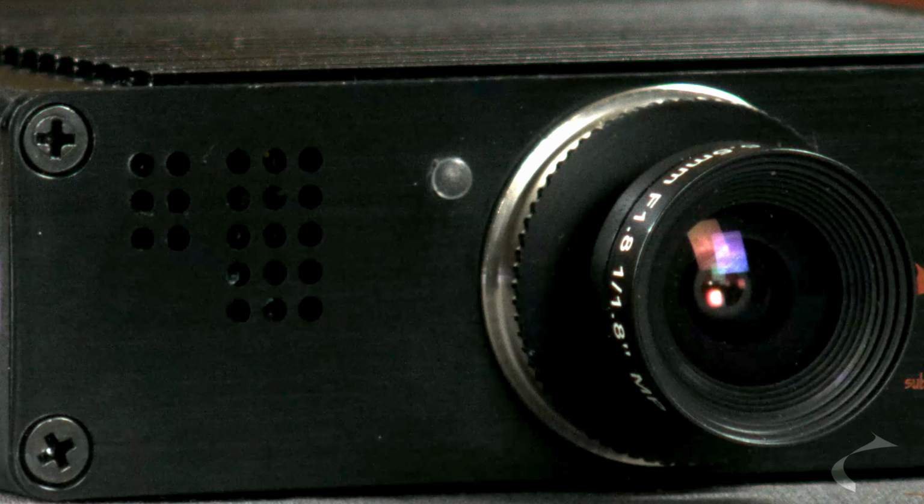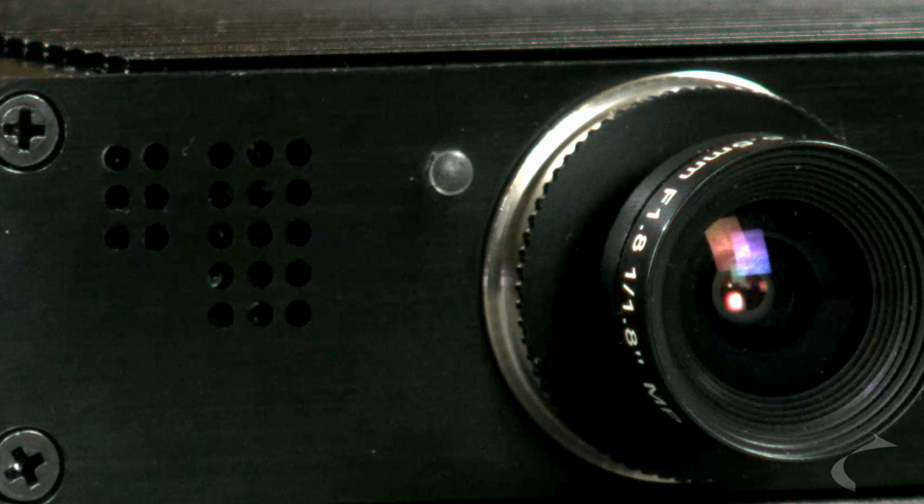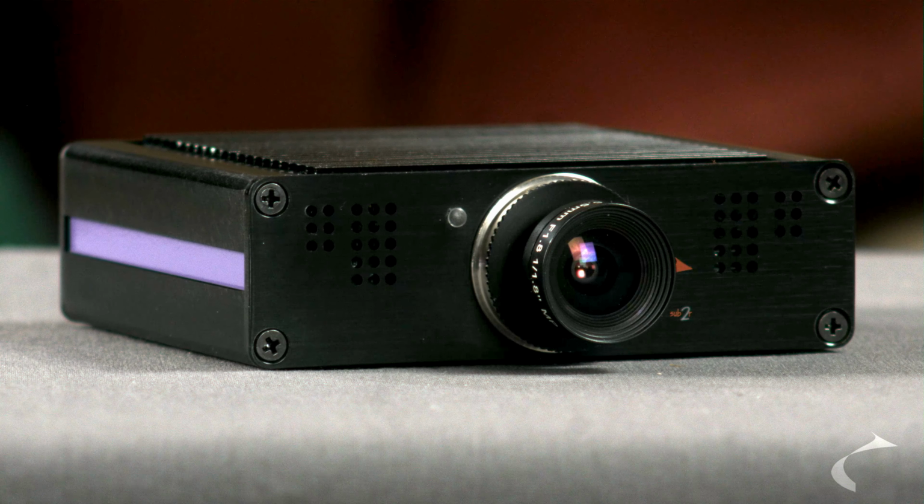LED indicator on the front panel of the camera can provide some diagnostics. If the LED does not turn white, USB port does not supply enough power to satisfy the minimum requirements. If the LED is dim or flickering, power supplied by the USB port is insufficient. If the LED turns white but after 5 seconds does not turn green, there is insufficient power to run the main processor.